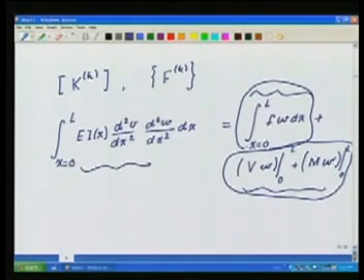Okay. So if I look at first the stiffness part, where is it going to come from? The stiffness part will come from the partitioning over the element k: sum over k of the integral from x1 of k to x2 of k of EI times V double prime W double prime dx. I am now writing the second derivatives as double primes.